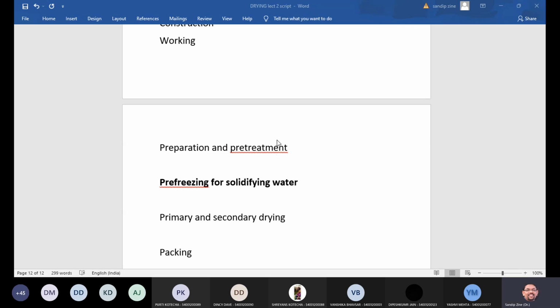Also, in case of primary drying or secondary drying, what will happen in primary drying? After pre-freezing the product, conditions must be established in which the ice can be removed from the frozen product through sublimation, resulting in a dry, structurally intact product. And this requires very careful control of two parameters. The first point is about temperature and pressure involved in the lyophilization system. The sublimation rate of the frozen product depends on the difference in the vapor pressure of the product compared to the vapor pressure of the ice collector. Also, the molecules migrate from the high pressure sample to a lower pressure area.